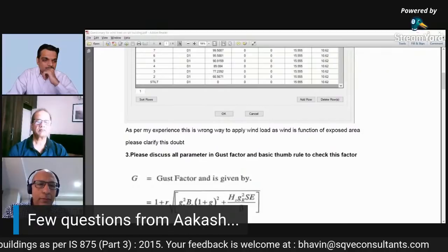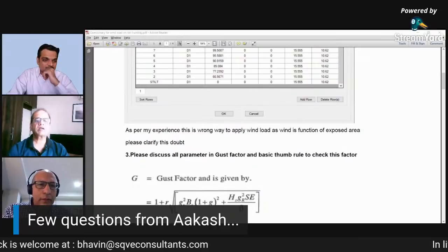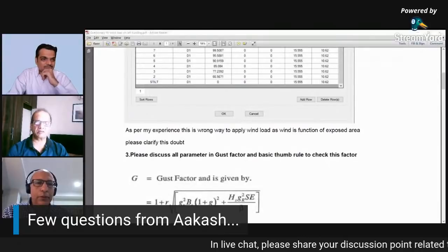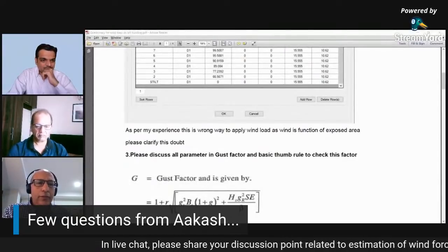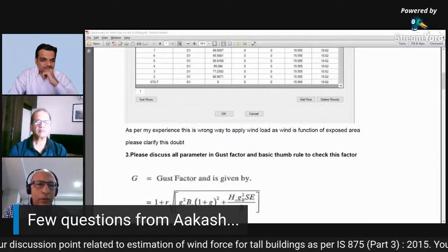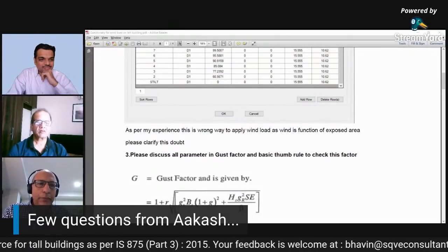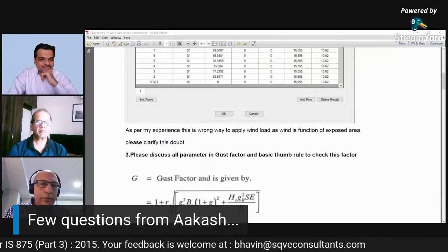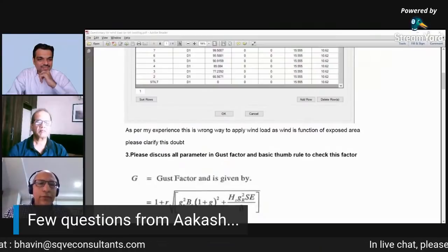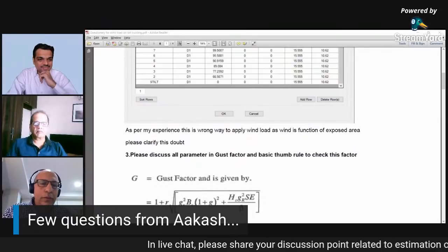If it's a very tall building, then you simulate the loads to a point, say, at the center of rigidity, as long as it's obviously including a torsion component as well. Then what Dr. Gupta said is true for low rise, mid rise. For very tall buildings, what happens is, because we're applying these loads all the way up to the top with a component of torsion, they would tend to have the same effect. The effect will not be very different.